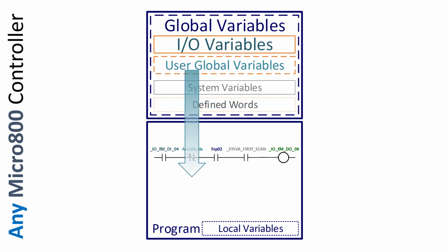The second instruction, a reverse contact, true if off, reads the on-off state of the memory location that it is addressing. If that bit is off, then the instruction is true. Again, that second instruction, reverse contact, true if off, reads the state on-off of a memory location that it is addressing. If that bit is off, then the instruction is true. Consequently, if that memory location is on, then the instruction is false. So here's where I like to point out why I call these true if on, true if off. It just cuts right to the chase. Reverse and, direct contact, reverse contact just don't do it for me personally.